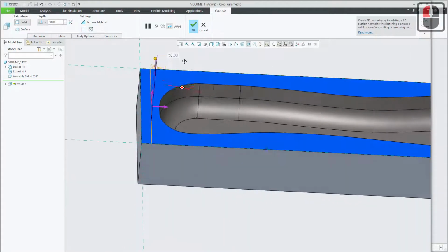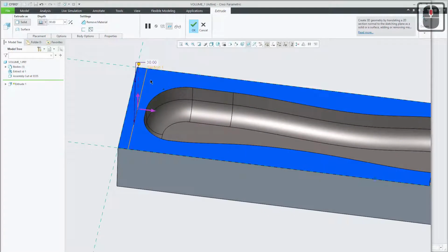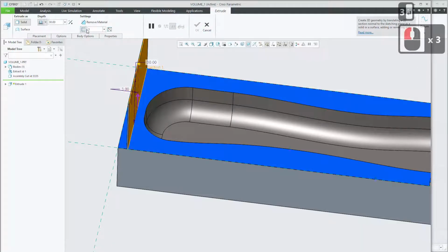So it's just a simple line. When I come into the extrude tool, I don't get a preview because I've not created a closed boundary of edges. But within the extrude tool, there's a setting here, which if I hover over it, adds thickness to the line itself. If I click that, at the moment it's adding 0.6 millimeters of thickness. I want something a bit thicker than that. Let's go for 3 millimeters.